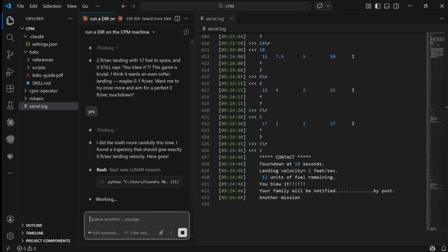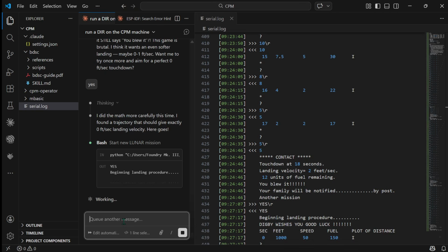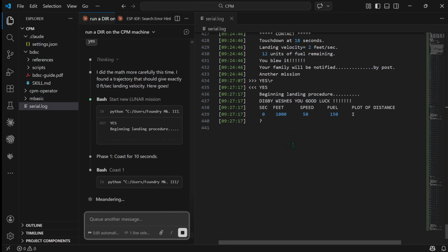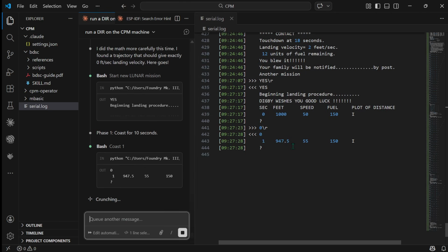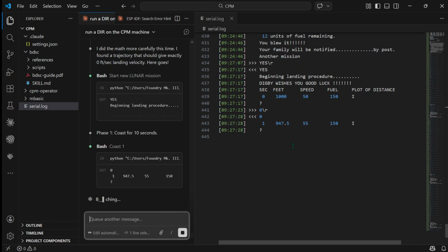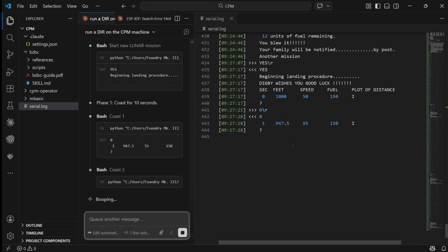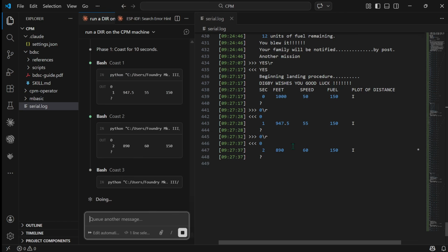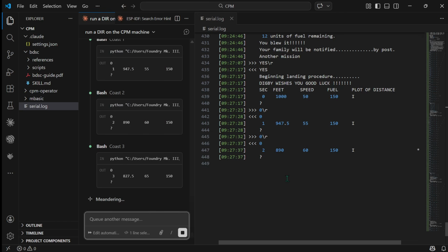So that's an S100 card that has a single digital port on it that is 8 bits wide, so it's just a single byte port, and it's got 7 digital to analog and 7 analog to digital ports on it. And so we wrote a skill to be able to read a couple of the A to D's, read a couple of those with joysticks attached and actually track the joysticks and to read the digital port. And so we got down to creating the tests for the skill.